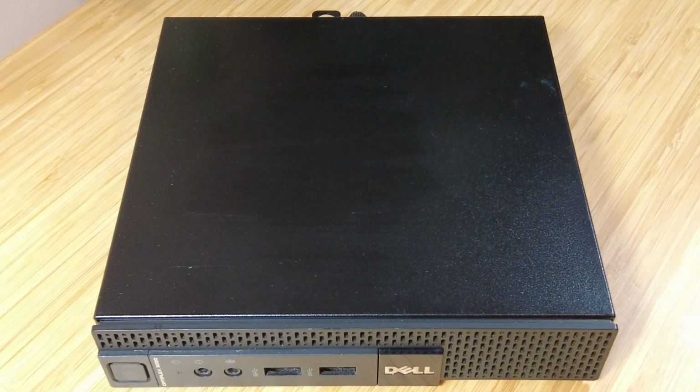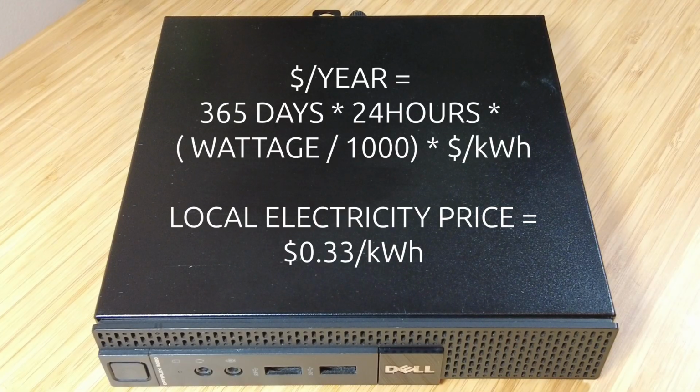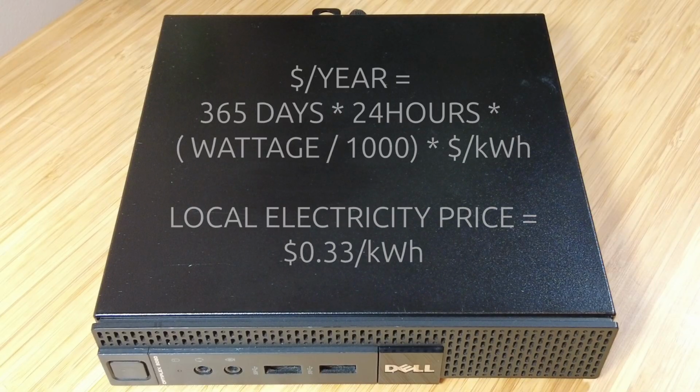Now that I've transferred the container, I want to look at the running costs per year for each of the machines. Now, the dollars per year to run will equal 365 days times 24 hours times the wattage divided by 1,000 to convert that to kilowatts, times the price per kilowatt hour. And where I live, each kilowatt hour is approximately 33 cents.